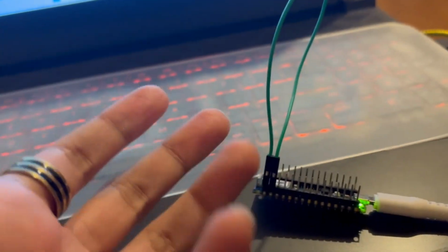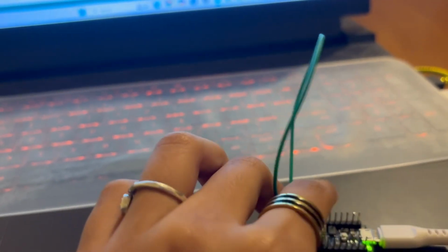Even though the SAMD21 has 64 pins, all those physical pins are not actually mapped to all the peripherals of the board itself. So that's why we get these numbers and the total doesn't add up to 64.